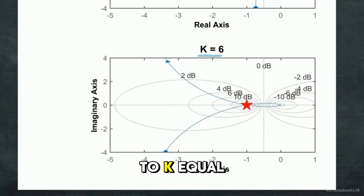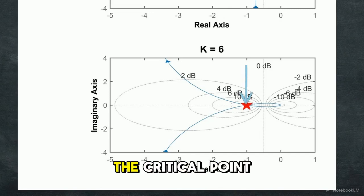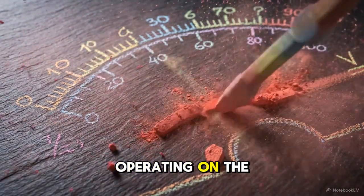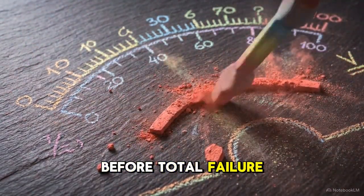Pushing the gain to K equals 6 changes the chart entirely. The crossing is now precisely at -1. The curve strikes the critical point dead center. This exact state of intersection defines marginal stability. The system is operating on the absolute razor's edge before total failure.